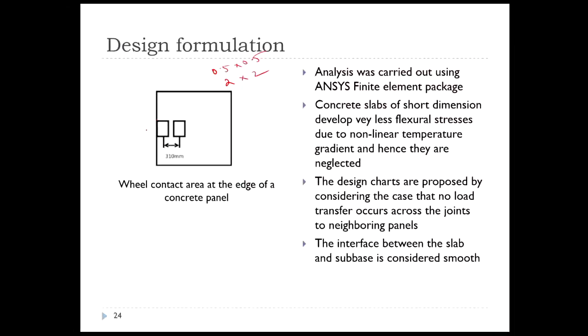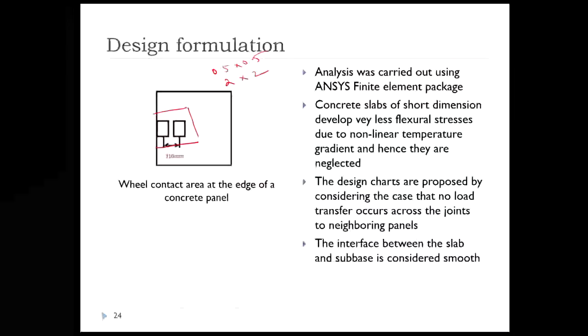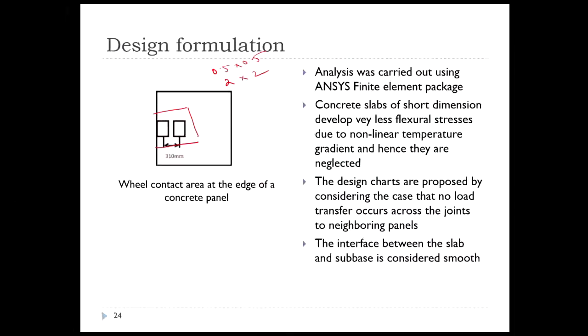This is the loading consideration they have taken: a dual wheel load of 50 kilonewton with a tire pressure of 0.8 MPa. The analysis was carried out using the ANSYS finite element package.